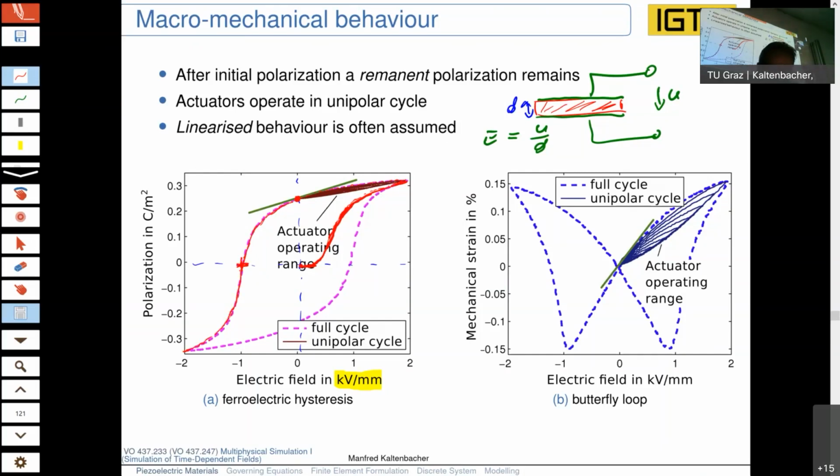And you again come to saturation. If you reduce and reduce the applied electric field, we again come to a remnant polarization, now just in the opposite direction. Yeah, and if you apply again a positive voltage, then you close your hysteresis loop, as you can see. Yeah, and it is clear you have a lot of hysteresis loops there.